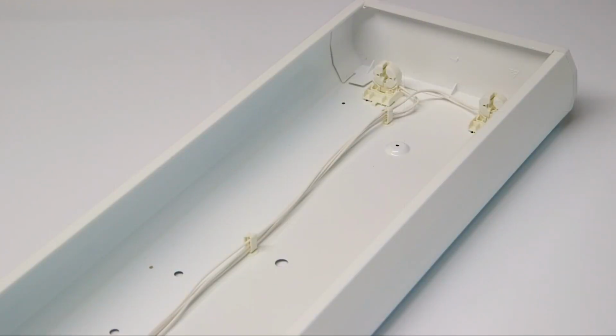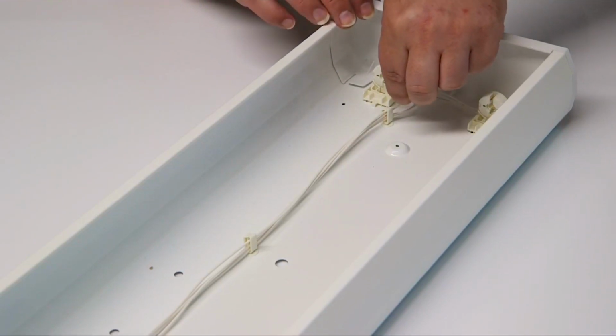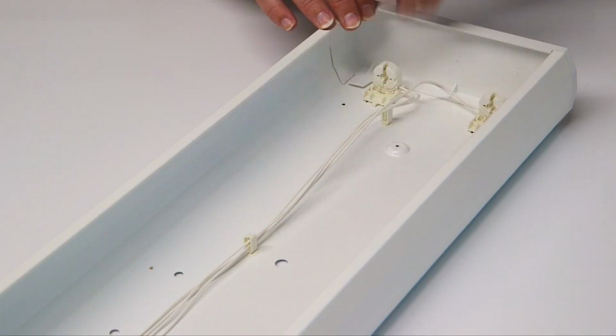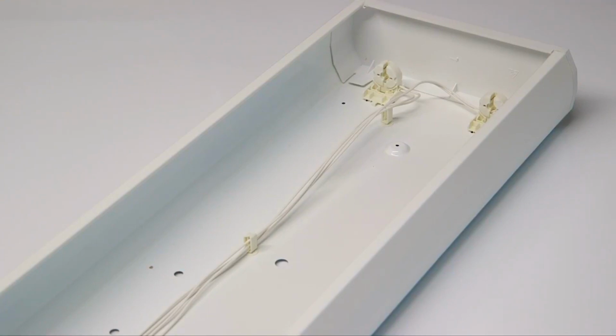To modify for our T-Lux T8 series tubes, the fitting needs to be rewired so that live and neutral are present at one end only, as the tubes are single end powered. The next step is to identify the most suitable end for this based on the length and position of the wiring within the fitting. On this fitting, we will select this end, as there are 2 independent wires per tube connector, as opposed to the other end where there is only 1 independent wire per tube connector. We will be disconnecting the ballast that we looked at and discarding this as it's not required for the LED tubes, and if left in circuit, it will consume power and reduce the overall energy saving.